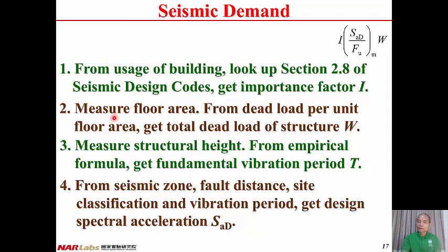Step 2, measure the floor area. From the dead load per unit floor area, which is given in advance, get the total dead load of the structure, W.